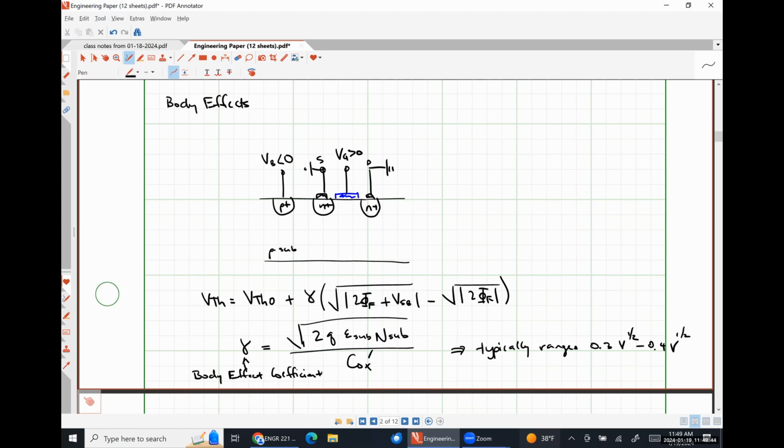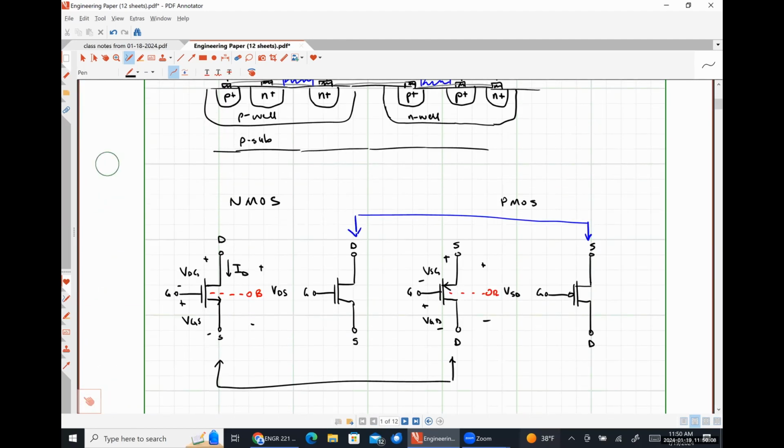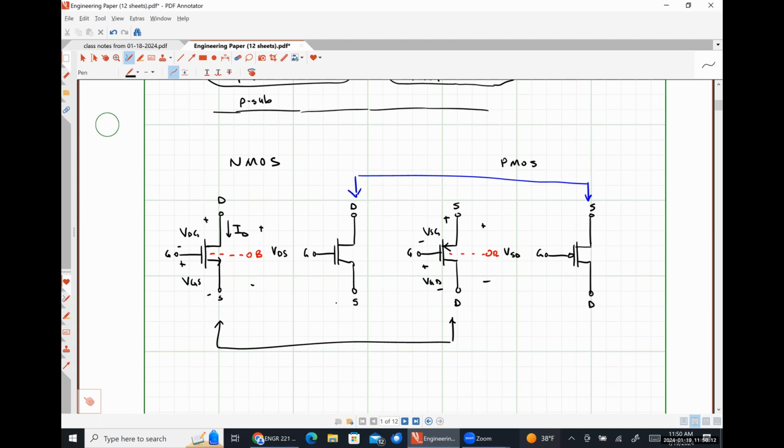So now let's delve into the interesting stuff. What happens when we allow the source or the drain to not be grounded out? So effectively, what happens when we try to get some current flowing through this thing? Actually, that brings back another thing really quickly here. In our schematic diagram representations, our device current or our drain current is shown as a current that flows from the drain to the source. I didn't put it here, but in this one, it'll flow in the same direction, from the drain to the source.